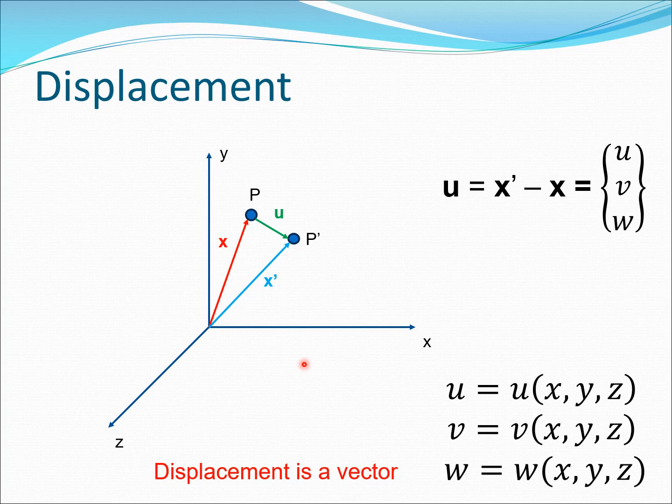So we can look at displacement itself in this form. For example, let us set up a coordinate system x, y, z, and then let's look at a certain point P here. Let's say the point P can be represented by a vector x. This is a very simple case in any kind of vector situation, because you are dealing with a three-dimensional coordinate system. You will have a vector x and you can represent the point P here. If you recall unit vectors in physics, you could say these have i, j and k components in the x, y and z direction. Now let's say this point has moved to some point P dash, and this is the displacement which has taken place for this particular point, and this point is in some solid. So at this point P dash, the position vector has shifted to x dash.